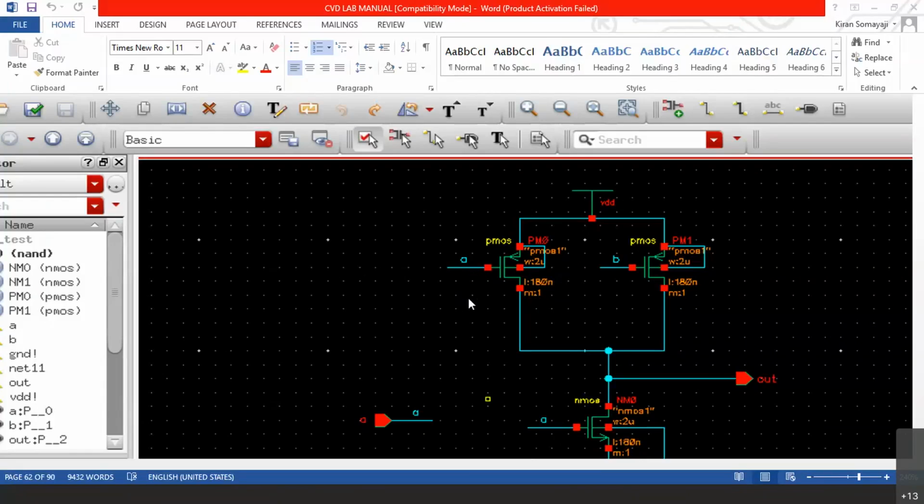Then they came to understand that the metals will have their own issues, parasitic issues, and the metals will have larger area. Then they invented a process of polysilicon, where we already know that the gate does not need any gate current. That is when they thought gate material can be polysilicon. Wherever we want to take it out of the chip, then we will connect it to a metal and take out a wire outside. Otherwise, inside the chip, it can remain as polysilicon.